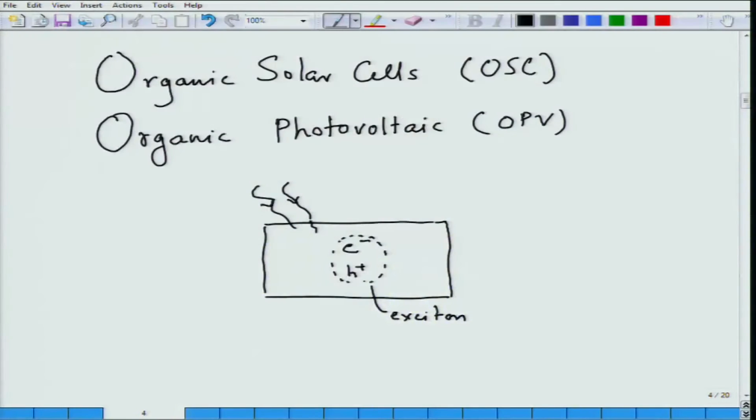When the light shines on this semiconductor or in this device, which we will build a little later, there will obviously be some amount of reflection that takes place at whatever the surface from which the light enters. So, the first type of losses that you can consider as a challenge to organic solar cells is the reflection loss, or sometimes people talk about it as the coupling of the light with the device.